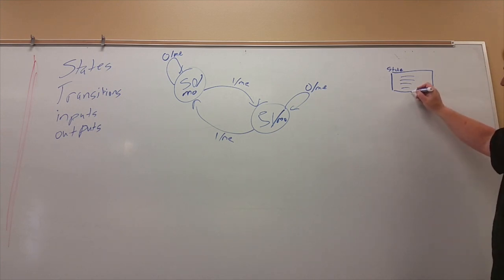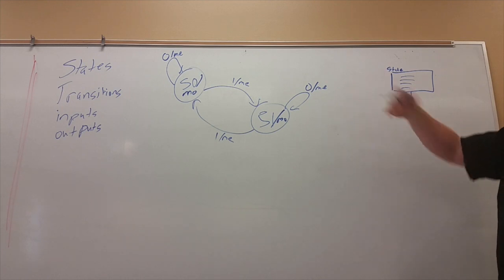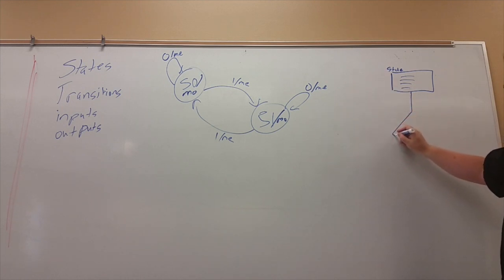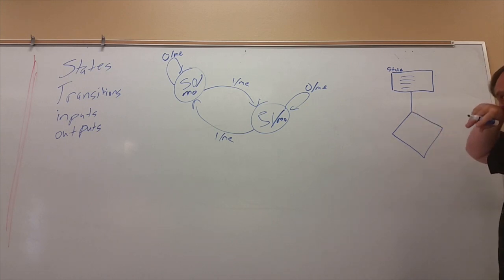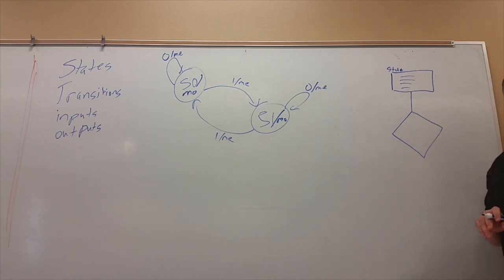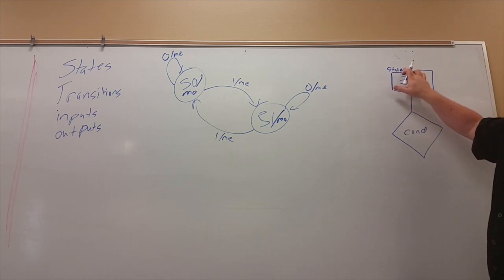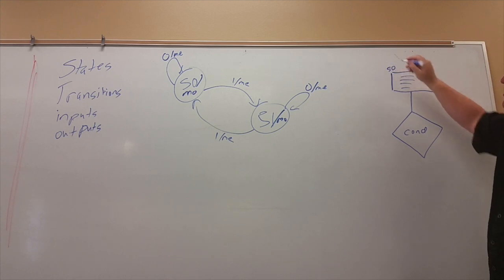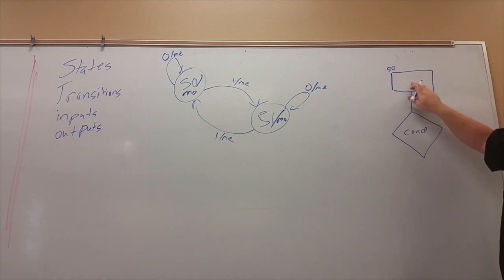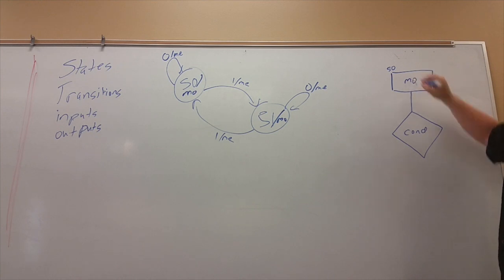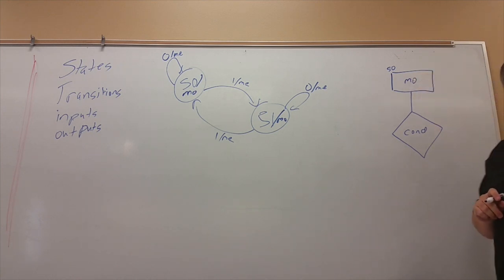Okay. Now this state, I have to be able to decide where my transitions are. So this is the classic, what's called a decision block. It looks like a diamond. Inside here you list some condition which is typically evaluated to true or false. So for instance, if I was making this state S0, and I wanted to make a Moore machine, I would put my Moore output here, just inside the state.